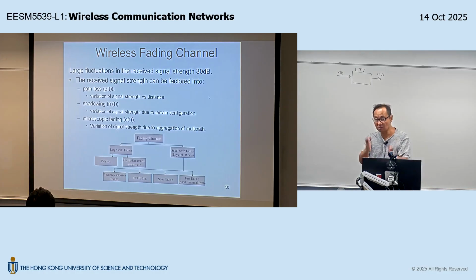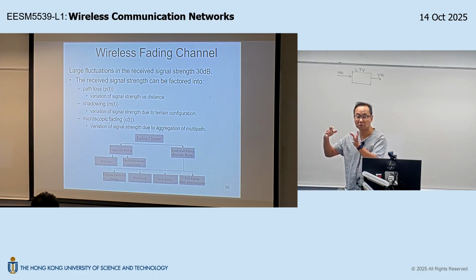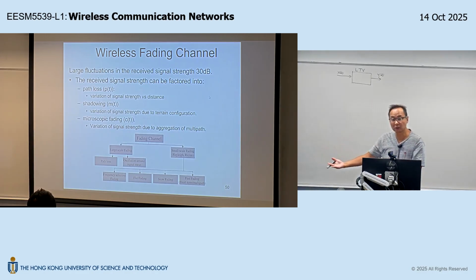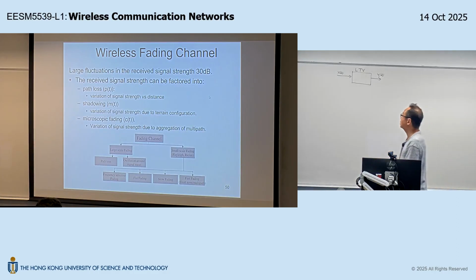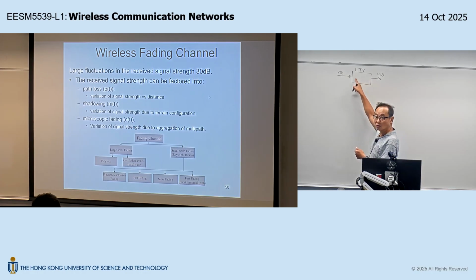If you observe the channel behavior at t equals 0, you get one behavior. One minute later, you will get another kind of behavior. So this is a time varying system. But fortunately, this is linear, so we still can parameterize the behavior using a two-dimensional impulse response.